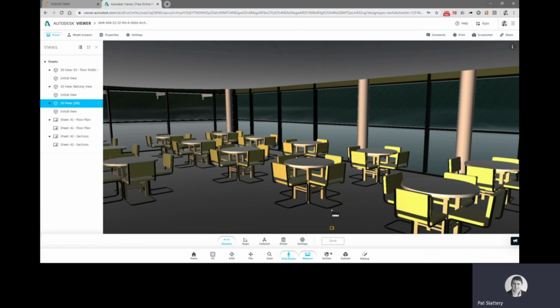It has got measure tools, so we can measure from different points. If you have a point to measure from, you can measure the points. It gives you the distance and the X and Y dimensions. I can measure from, say, floor to ceiling. Even if I don't, it will snap to the ceiling. So it'll snap to perpendicular, but I can measure. If I measure off at an angle, it will still give me the vertical dimension and the X dimension. But once I'm close to being vertical, it will snap and it will just give me the vertical dimension.